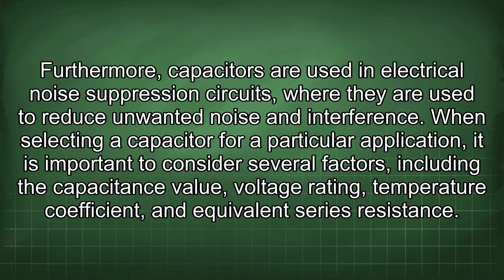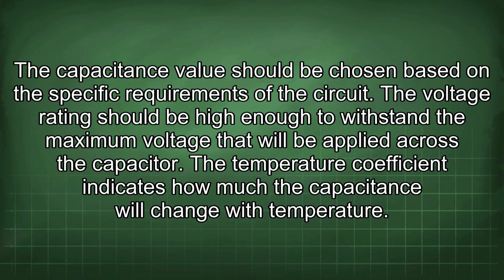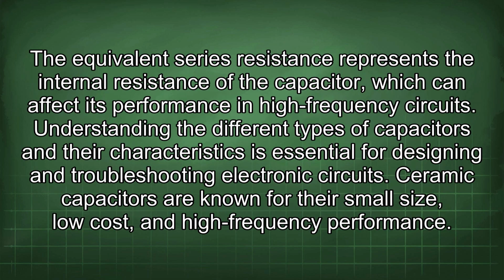When selecting a capacitor for a particular application, it is important to consider several factors, including the capacitance value, voltage rating, temperature coefficient, and equivalent series resistance. The capacitance value should be chosen based on the specific requirements of the circuit. The voltage rating should be high enough to withstand the maximum voltage that will be applied across the capacitor. The temperature coefficient indicates how much the capacitance will change with temperature. The equivalent series resistance represents the internal resistance of the capacitor, which can affect its performance in high-frequency circuits.